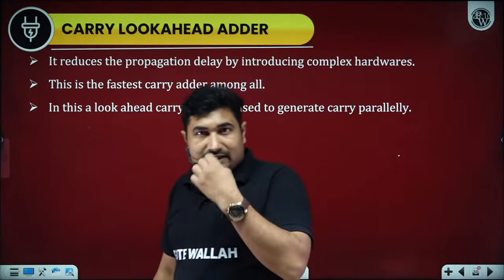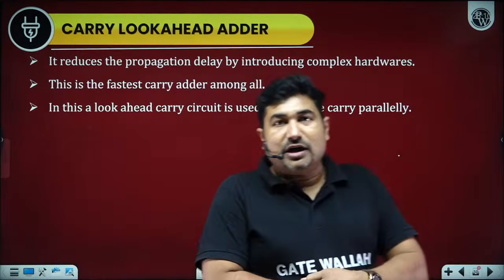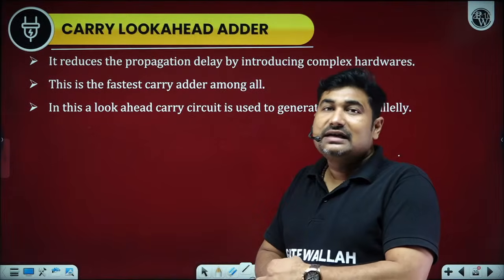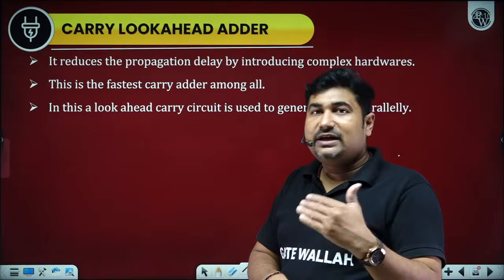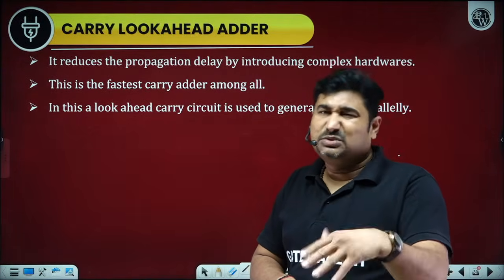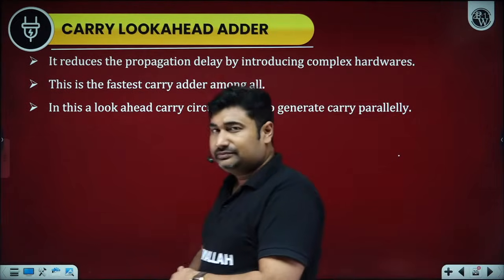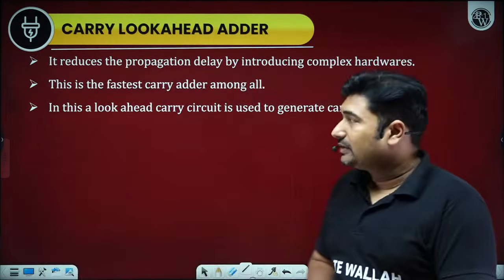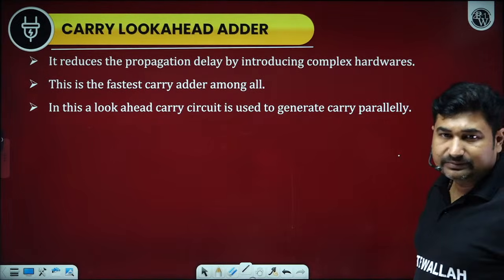Is it okay? Yes, sir. This is possible with a simple circuit design called the carry look ahead circuit. If we design a carry look ahead circuit or look ahead carry circuit, both are the same thing, in different books they have represented it in a different way, then we can do the addition directly. So let's have a discussion of the carry look ahead adder.